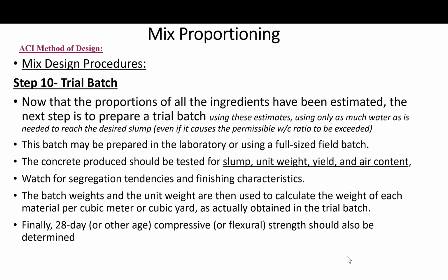Okay, so this batch may be prepared in the laboratory or using a full-size field batch, which actually I prefer. The concrete then produced should be tested for slump, unit weight, yield, and air content, as well as observed for segregation tendencies and finishing characteristics. So this trial batch really goes a long way to help you fine-tune your mix and anticipate any problems and know what to expect. So you make sure you mitigate any potential problems before you actually pour the concrete.